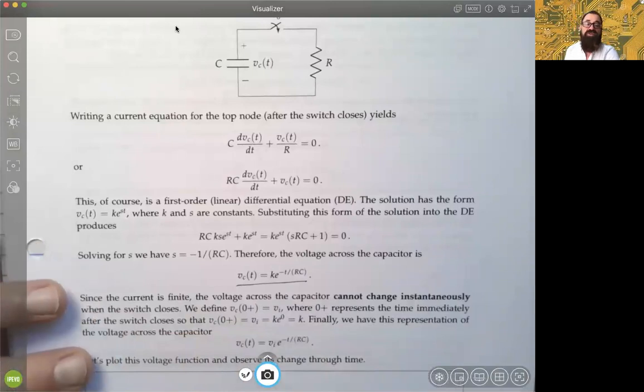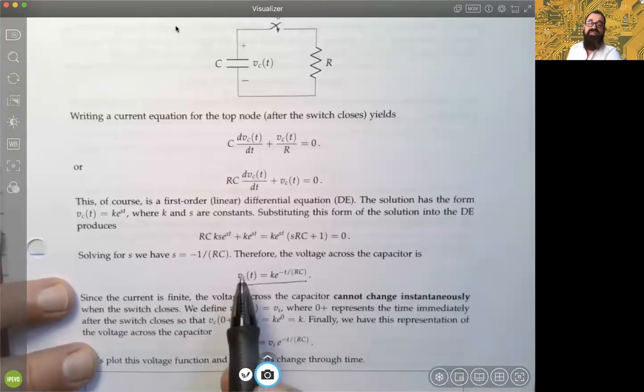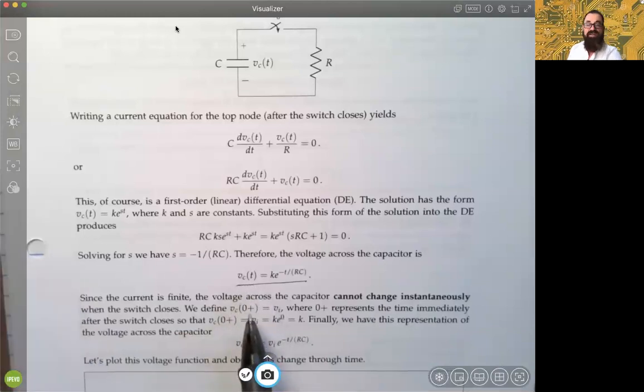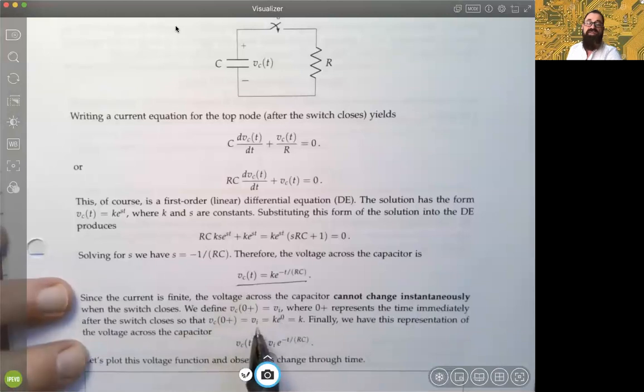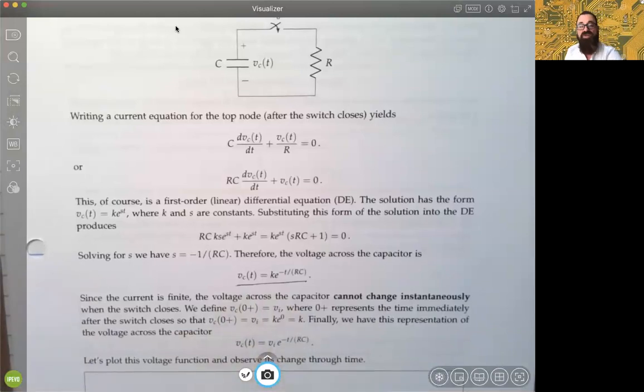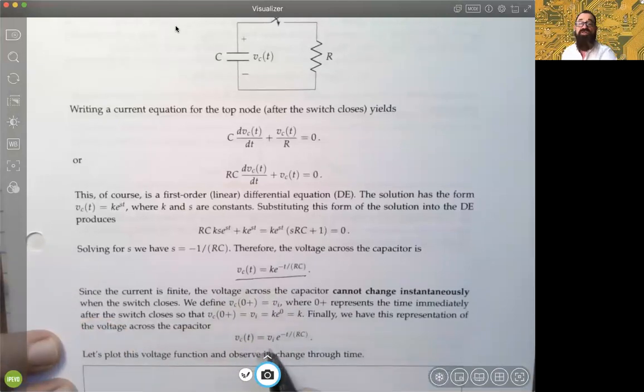And so if we do have V_I voltage there, then what we would do is set this function V_C of t right after time 0 equal to the initial voltage, plugging in time 0 here at the top. If we do that, then we'd have k times e to the 0. So that tells us exactly what that constant will always be: the initial voltage on your capacitance.